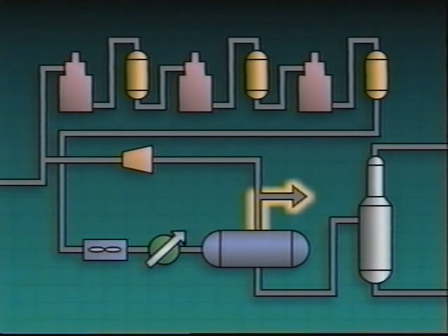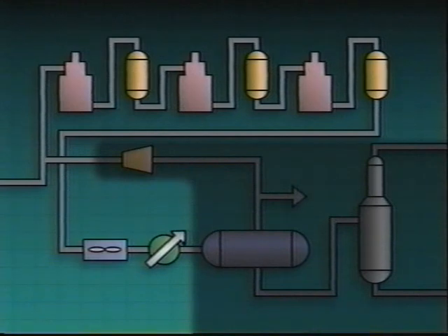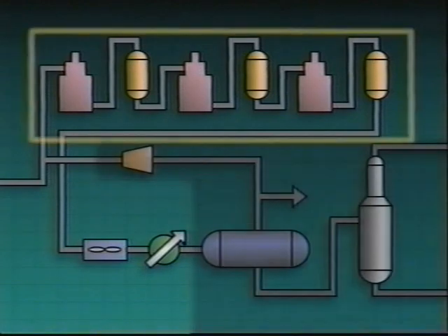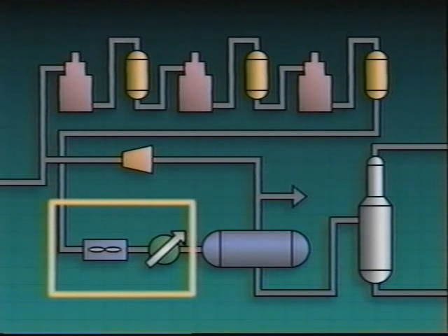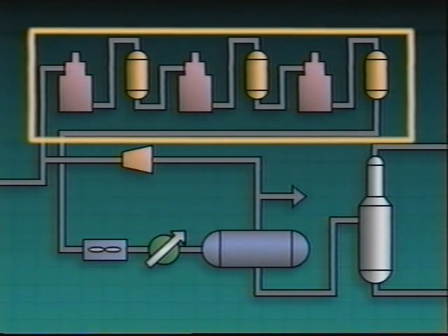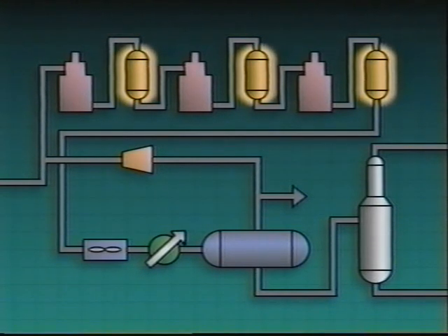In addition, although the hydrogen make is high, the hydrogen recycle rate is checked and found to be normal. So the recycle compressor is working properly and can be eliminated as the cause of the problem. This leaves the rest of the equipment in the reaction section and the condenser section. We'll start by checking the process variables in the reaction section. A good place to start is by checking the reactor temperatures. If they're too high, too much of the product is converted into light gases, and the hydrogen make flow rate will go up. That's not the problem here, however.